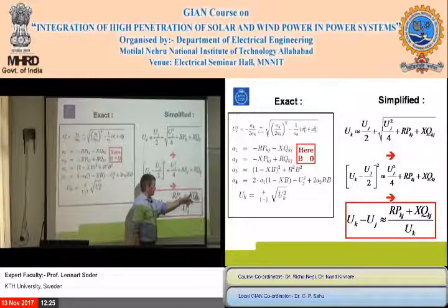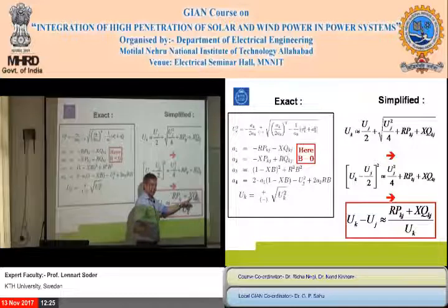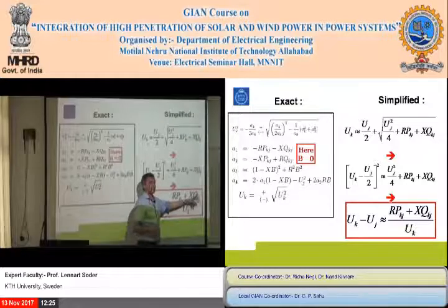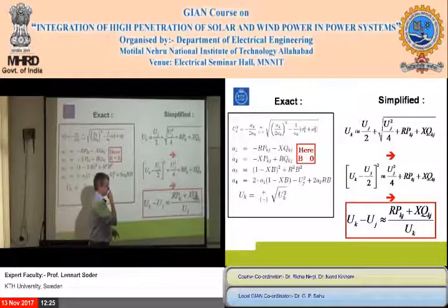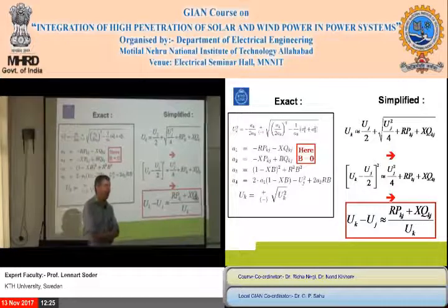Maybe. It depends on the size of the X. If the X is nearly negligible, as you have, for example, in a cable network, then you cannot do so much with the reactive power. But then you have another issue. Can I supply reactive power?